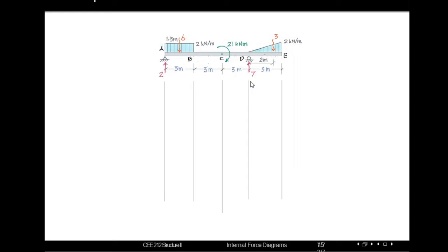Now let's draw the shear force diagram. Before drawing the shear force diagram we need to draw vertical lines at the starting point and ending point of the loadings, at supports, and at the point where there is an external moment. So now let's draw the shear force diagram.